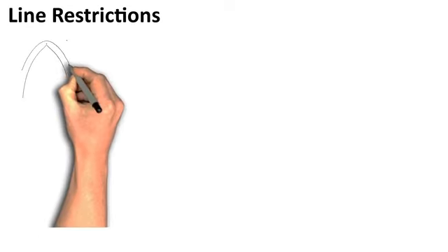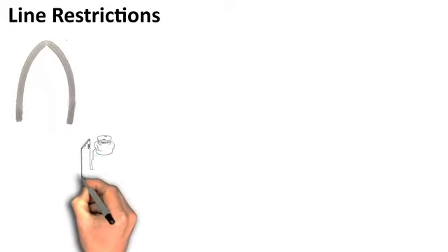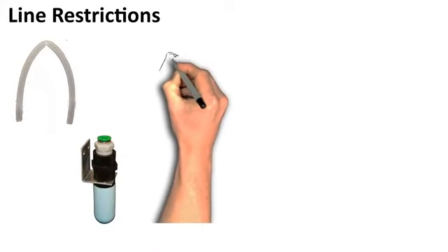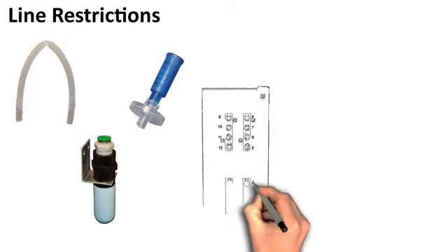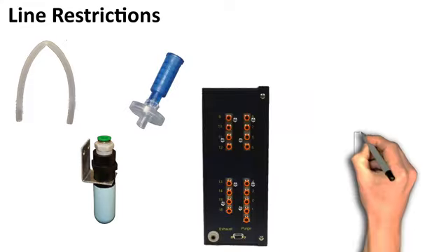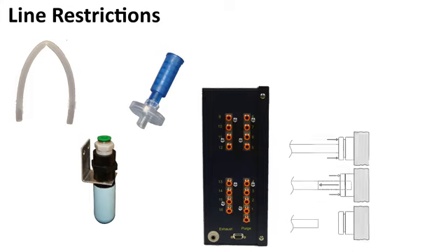If the diagnostic values indicate a restricted flow, there may be a clog in the sample tubing or a clog in the end-of-line filter. To diagnose these issues, locate the connector of the suspect zone on the side of the MZ chassis. Disconnect the zone tubing by pushing in on the connector while simultaneously pulling out on the tubing, effectively eliminating that whole zone.